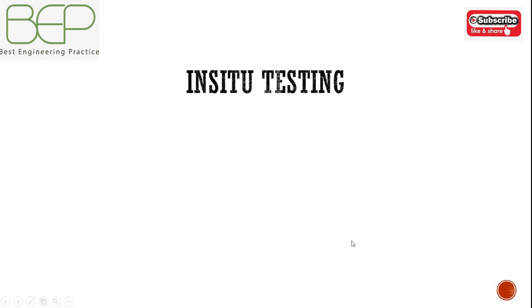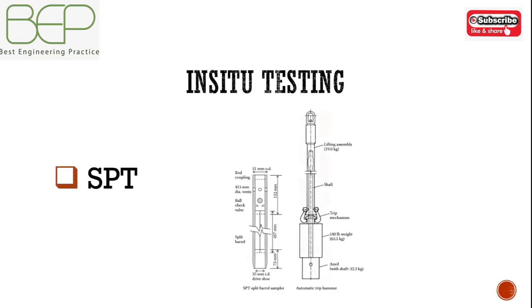The two main types of in-situ tests used around the world are the standard penetration test (SPT) and the cone penetration test (CPT). The SPT is carried out in a borehole and essentially involves counting the number of hammer blows that are necessary to drive the thick wall tube 300 mm into the ground at the bottom of the hole.